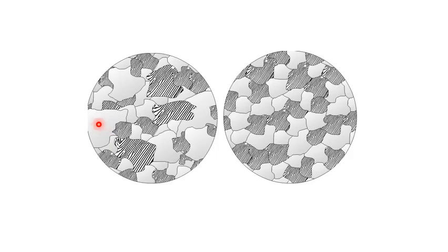because the chemical activity of metallic solids increases with the energy stored in the material. And because the energy stored in the grain boundary is higher than the energy stored in the grain, the chemical activity of the grain boundaries is higher than the chemical activity of the grains.